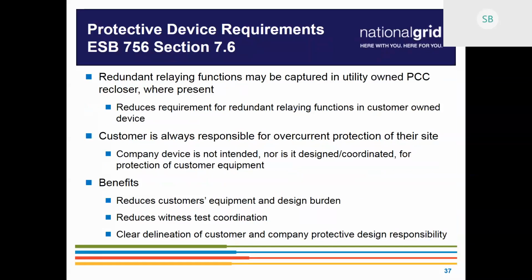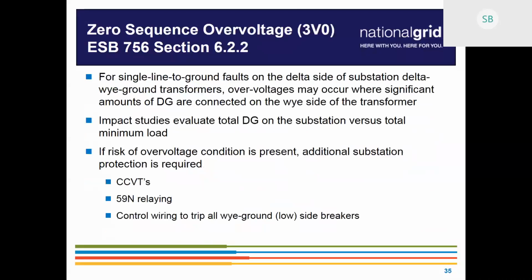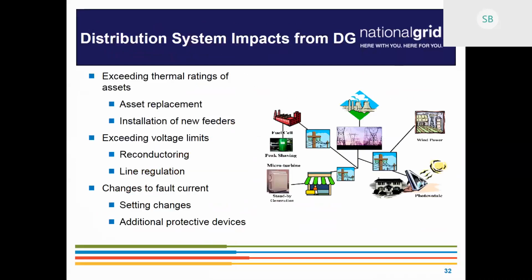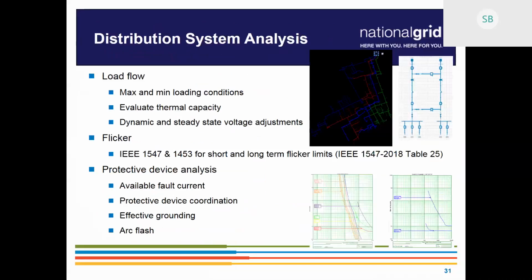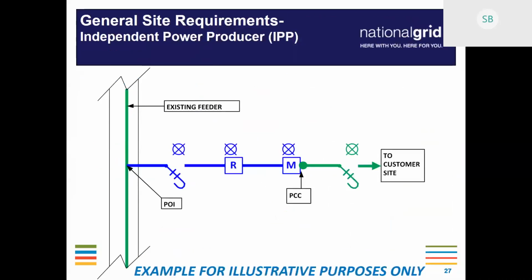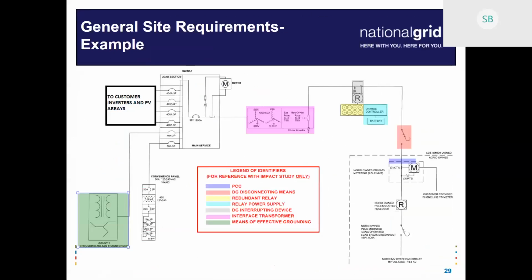Hi, Edwin Fo from Bloom Energy. Question regarding effective grounding. You highlighted in your impact study slides that you would conduct a review and evaluation of effective grounding. During the screening, the screeners do highlight that effective grounding might be required, and that could occur at project levels 250 kW and greater, right? I believe this was in the DSB. So does that then mean that any project greater than 250 would need to go into an impact study to be evaluated?